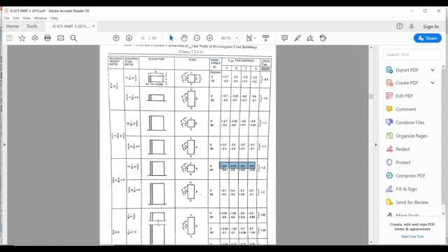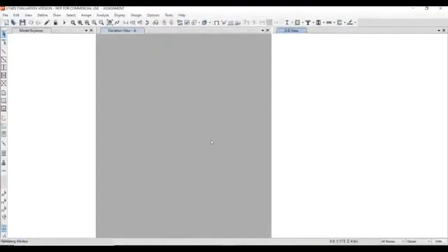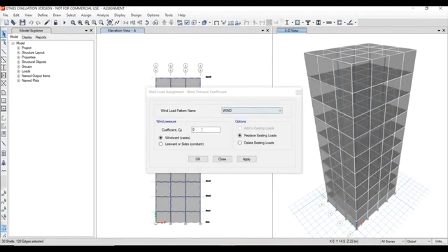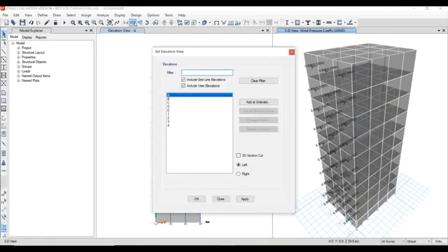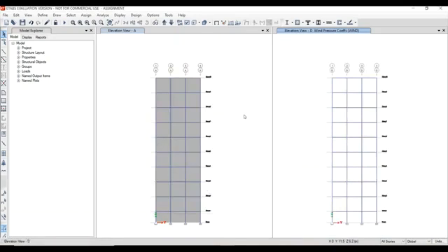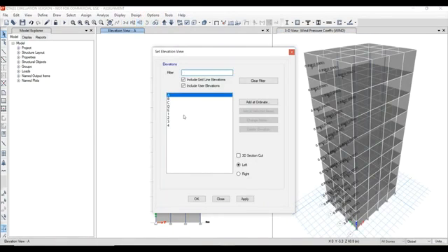So we need to enter these values in our model. So coefficient of plus 0.8 in the windward direction, apply, OK. And now in elevation view, select section D, apply and OK. Sorry, we need to select the elevation view on the tab where we had selected previously.